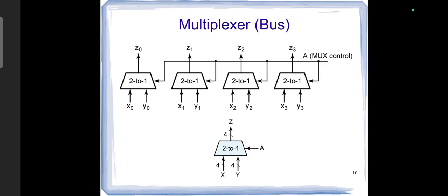One practical application of multiplexers is the multiplexer bus or bus multiplexer. A bus consists of multiple wires carrying binary data between different components. Instead of providing separate connections for every device, a multiplexer selects which device can send data through the common bus. This reduces wiring complexity, saves hardware, and improves system organization. Bus multiplexers are widely used in processors, microcontrollers, and communication systems.